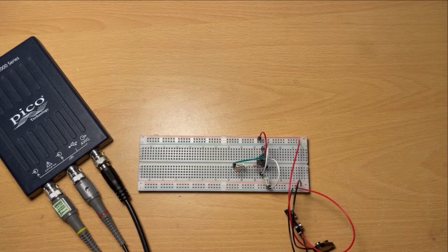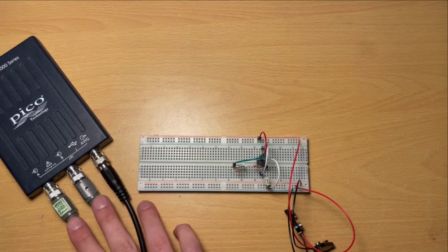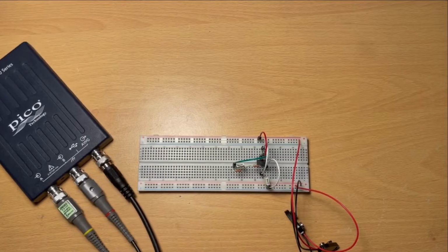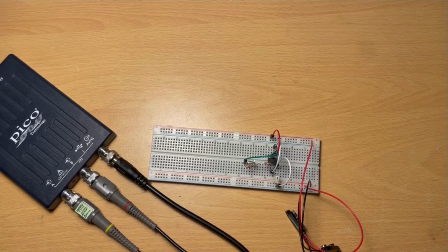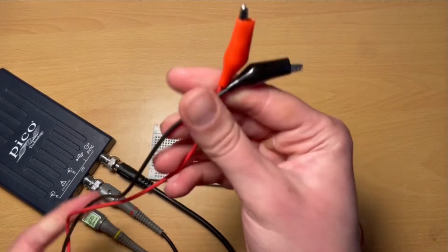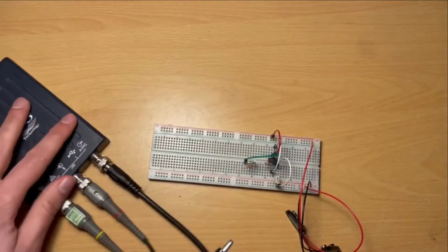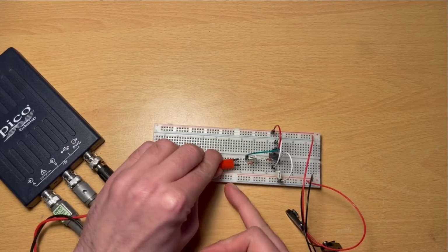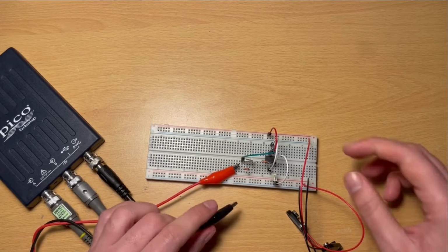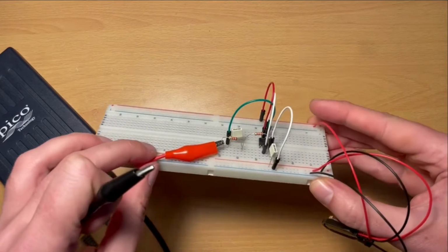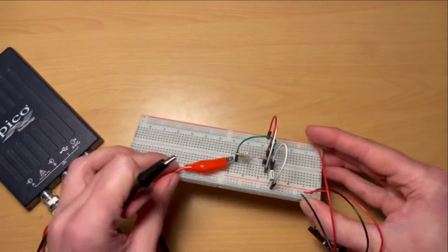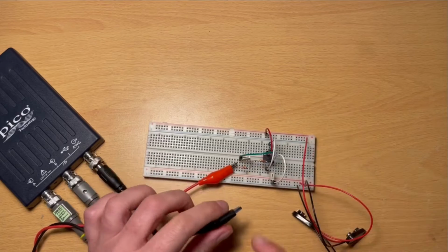So what we're going to do is, first of all, we've got those 2 channels on our oscilloscope, both of which have leads like this, but we're going to connect our actual signal generator first of all, which is a tiny bit different. What I've got is another coaxial lead there in that signal generator channel, but it leads instead to these crocodile clips. And so what I'm going to do is I'm going to connect the crocodile clip to the input of our circuit here. And so when we built this circuit in the previous video, our input was defined as that kind of leg of the first resistor sticking out there. If you've not watched the first video where we put this circuit together, it might be worth doing so.